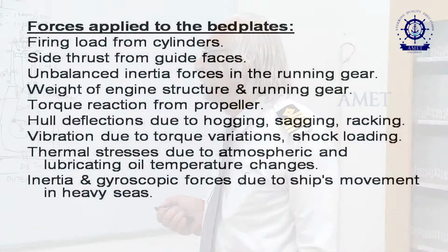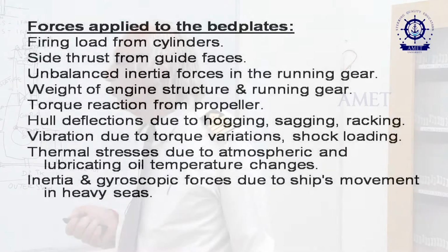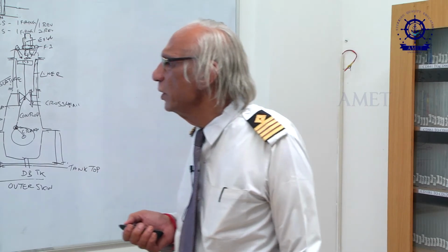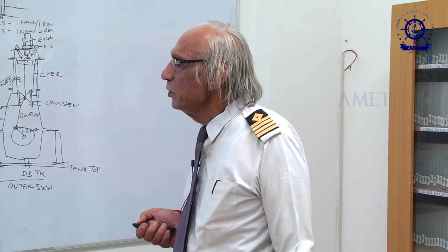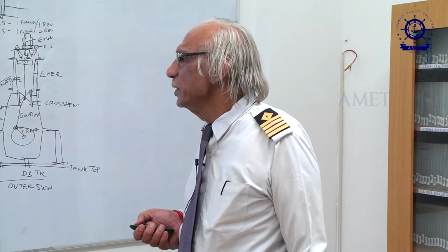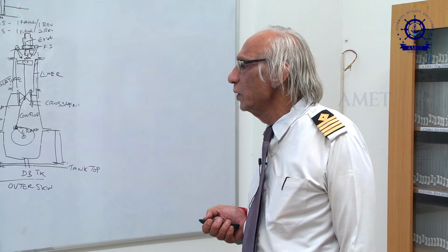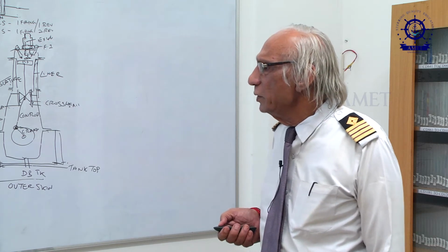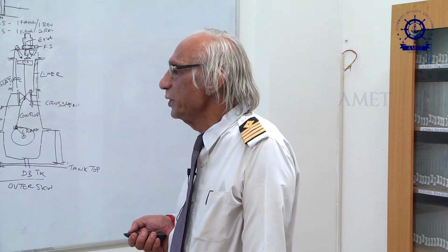In addition, there is vibration due to torque variation, because the propeller is not going to move uniformly. If you have many cylinders, then the turning moment of the engine will be uniform. But if you have only a small number of cylinders, then there can be variation in torque. You can also have some shock loading because the propeller is not moving in uniform water. Then the firing load causes thermal stresses due to atmospheric and lubricating oil temperature changes. And the bed plate is also subject to inertia and gyroscopic forces due to ship movement in heavy seas.